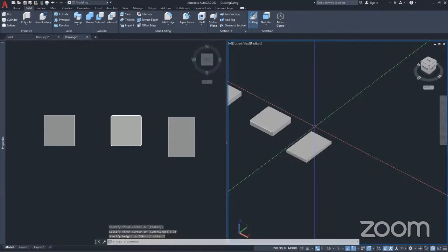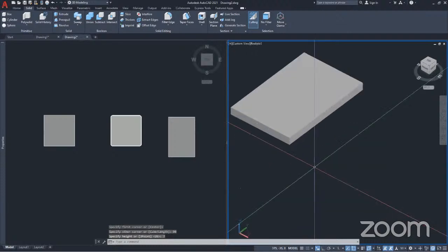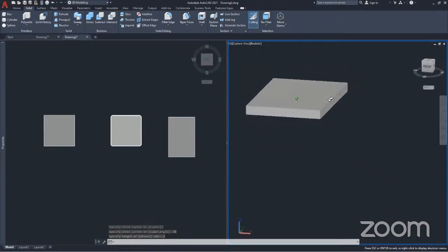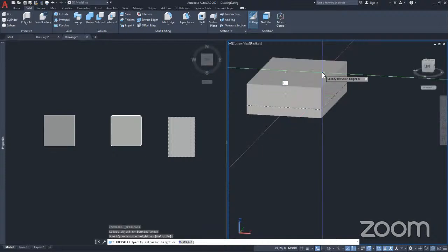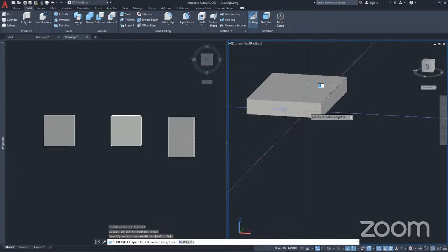Yeah, this box is too small though. I'll press pull it by 3 millimeters or 5. Make it so, yeah. I'll press pull this part inside also by 10.